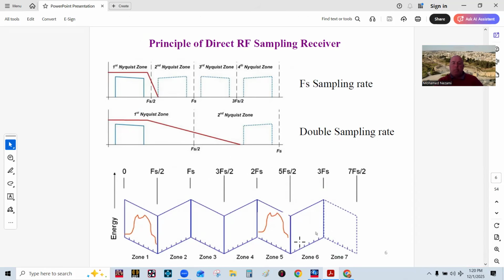Now, if an ADC is sampling at these rates, you can have an input signal as long as it's within the 3 dB bandwidth of the ADC, which has to do with the internal parasitic capacitance and internal impedances. It has nothing to do with the filters of the DSP or the aliasing filter.